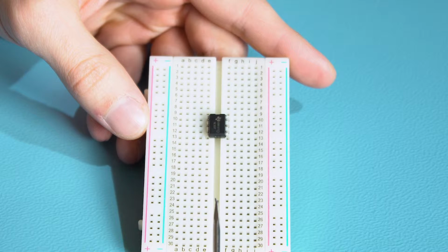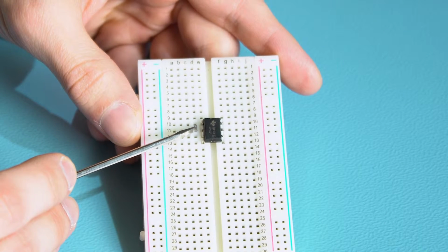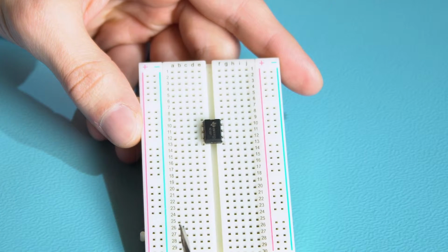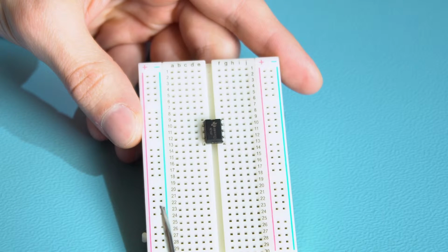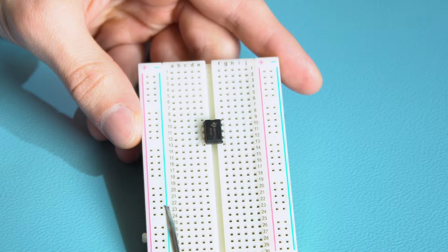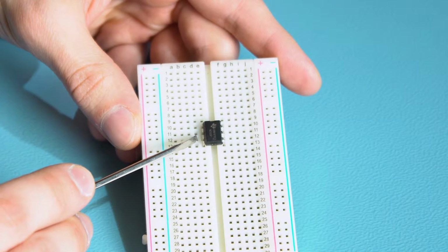At the moment of exceeding the voltage of 1/3 VCC, pin number 2 is set to high. This causes the low state to appear on its output because there is negation. The discharging transistor does not turn on, and this state is negated in order to obtain a high state, which is close to voltage of VCC, on the output marked as number 3.